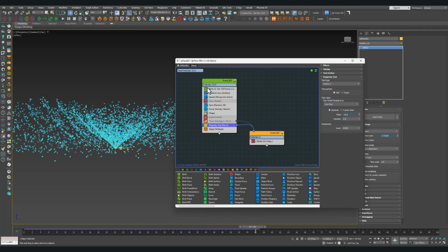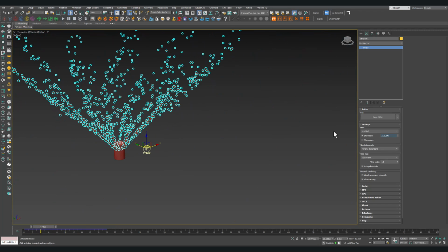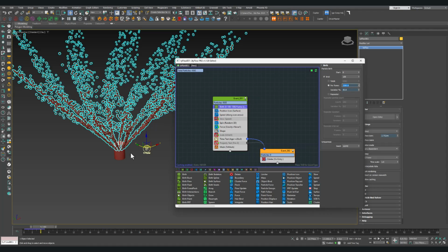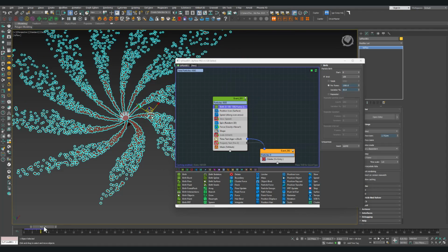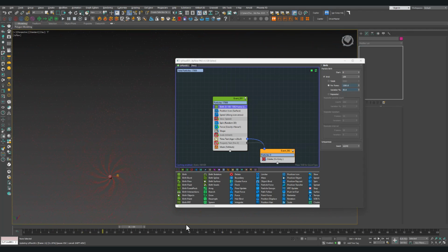to prevent producing lots of particles. Very simple. Or you can very simply use time test with the age of particles. And also don't forget to change the time step to 1/16, maybe more, to add more particles. Let me change it to maybe 1001 and 500 to have more particles, to have more details. You can see Tyflow is very fast. Let me show you.